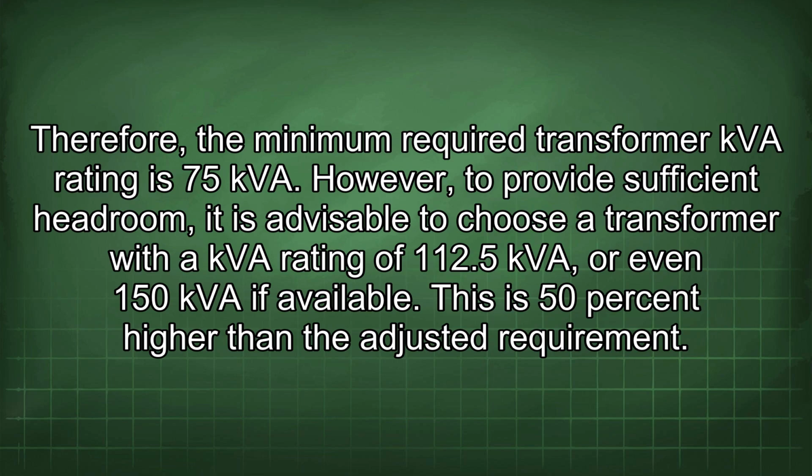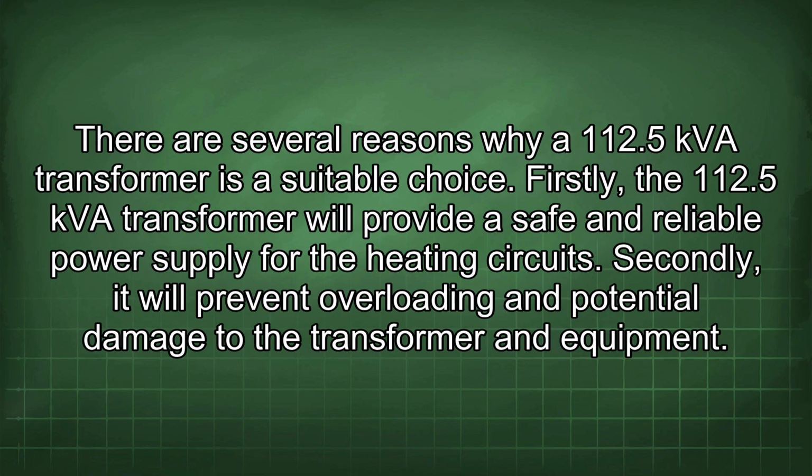However, to provide sufficient headroom, it is advisable to choose a transformer with a kVA rating of 112.5 kVA or even 150 kVA if available. This is 50% higher than the adjusted requirement. There are several reasons why a 112.5 kVA transformer is a suitable choice.